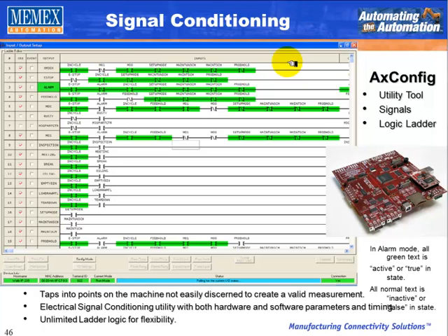It utilizes a package toolkit approach. It's really a utility tool. It involves logic ladders, very similar to a PLC logic ladder, which sets the different logic signals directly from the signals from the machine, interprets those in various combinations to be able to produce a particular output foreseen by OEE. In this particular example, on the chart, we can see that the alarm is green because all the individual signals are actually set as green to be true. And so the classic logic ladder works, and it works together. So it's a very quick and easy way to put it together. Let's spend more time looking at it in real time.